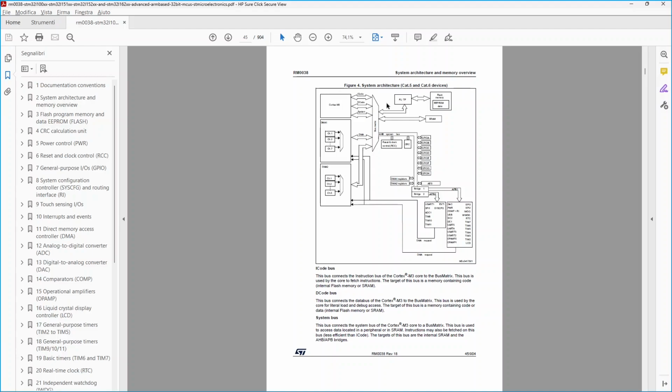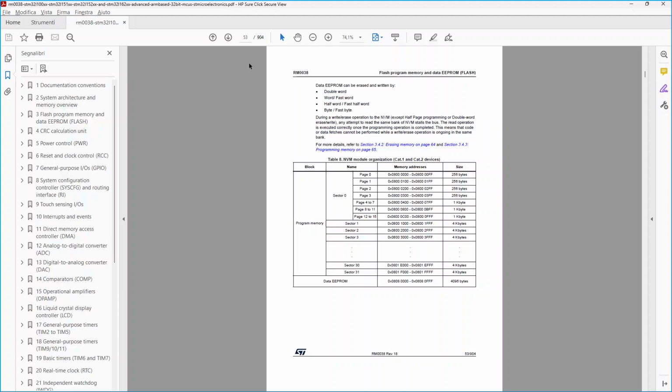That's the name in ST documentation. Handling flash and EEPROM with the same interface means that when an erasing or writing operation is running over a device, for instance on EEPROM, other operations cannot be executed on the NVM until writing completes. For instance, even reading the next program instruction from flash, so the program freezes.